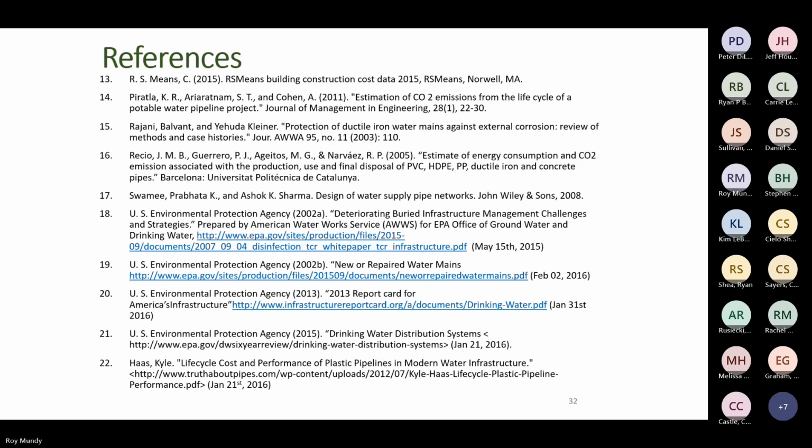And then it really comes back to, believe it or not, the great majority, 90% plus of leaks on pipelines is due to external loading. Engineers typically get the internal loading okay. They design the pipe for the proper inside pressure. But when it comes to the external loading, they don't get the soils right. They use native soil and compact it with PVC pipe, and then the pipe goes beyond that maximum deflection.